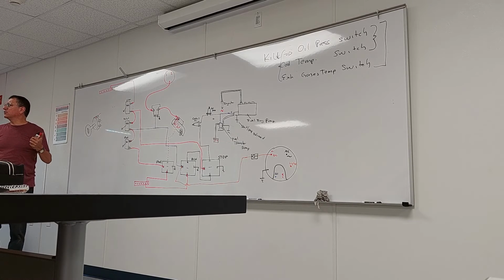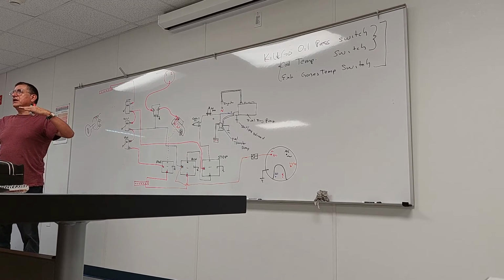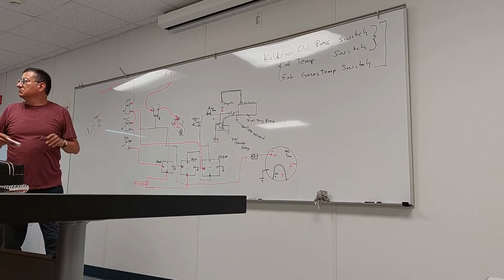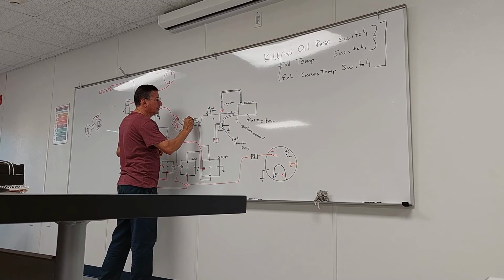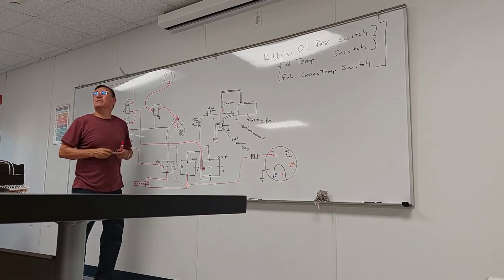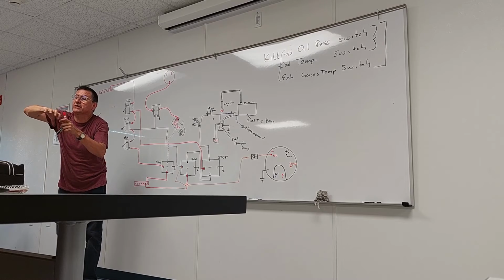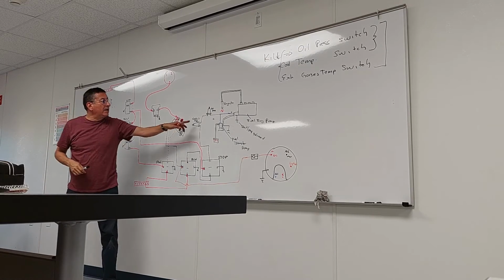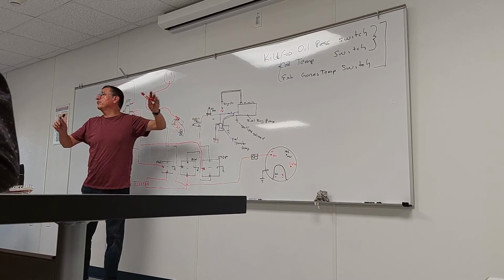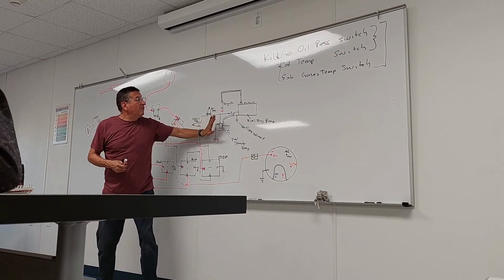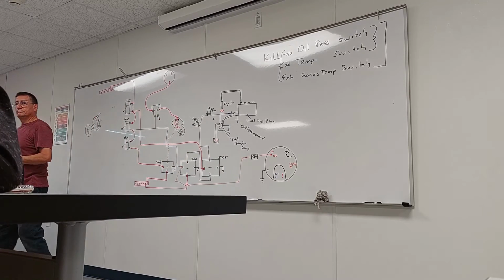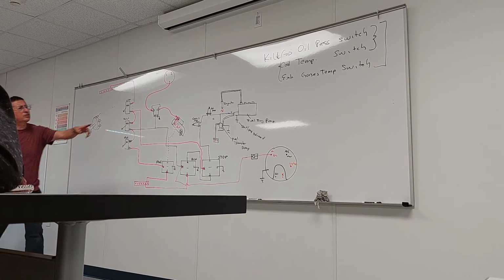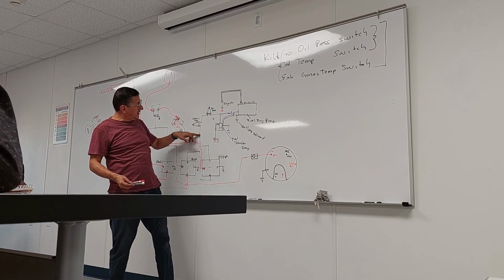Some manufacturers, like Detroit Diesel, interrupt the air. They have a wheel that closes the intake manifold, no more air enters, and the engine stops. The coolant temperature switch in the thermostat housing is located over there, and it interrupts the current and no more fuel. You interrupt the current to cut the flow of fuel. So all of those are killing the fuel. Also the exhaust gas temperature switch is located here for the same reason.